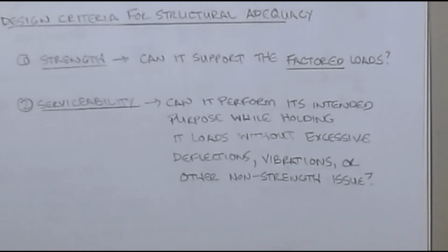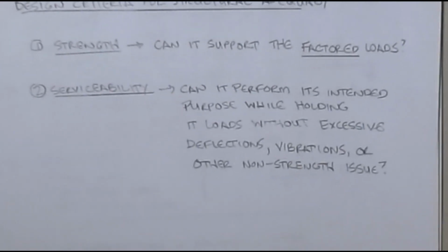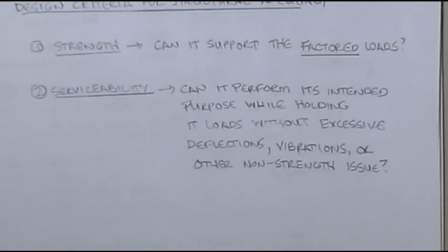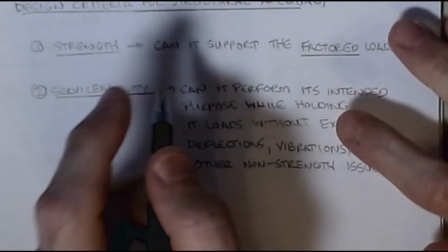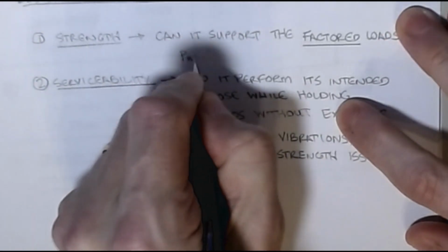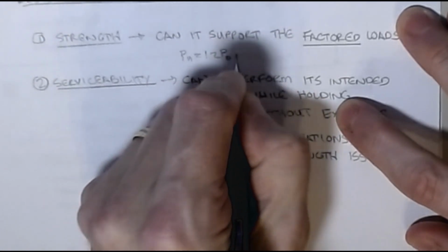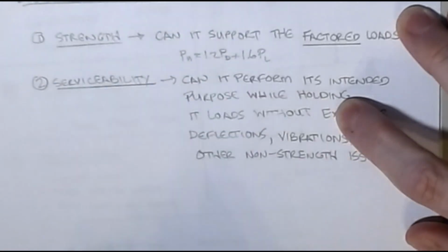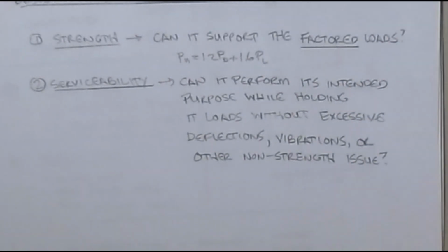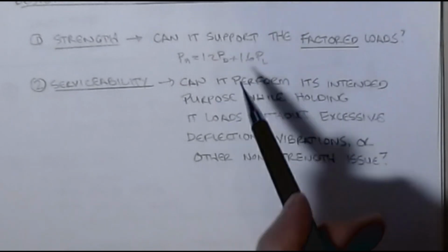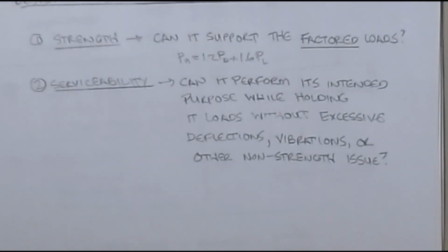Now, in the case of the loads for all of these, you'll remember that the LRFD methodology says that for the strength calculations, I have to factor the loads. These are those load cases of 1.2 dead load, that P_u is 1.2 P_dead plus 1.6 P_live, something like that. We use those to do our factored loads. And then with that, we compare it to the capacity side, the reduced phi, phi P_n, and the corresponding equations that come out of the AISC specification.